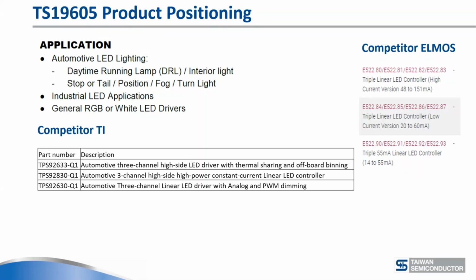We started designing this device about 18 months ago, of getting the heat out of the device, and in the meantime TI also launched the first one, the TPS92633, that has the automotive 3-channel high side LED driver with thermal sharing. So the thermal sharing is there in that device too. It's done differently from the way we do it.